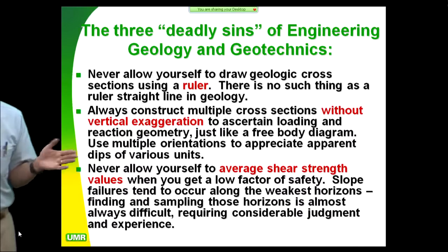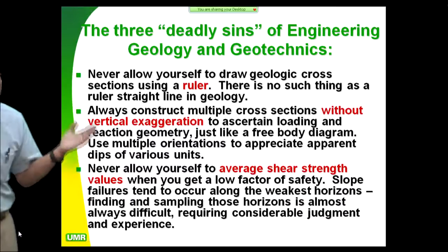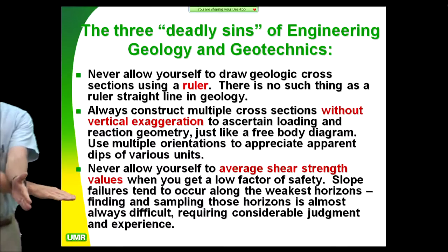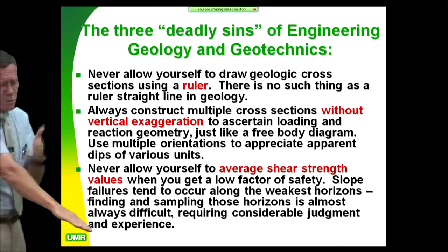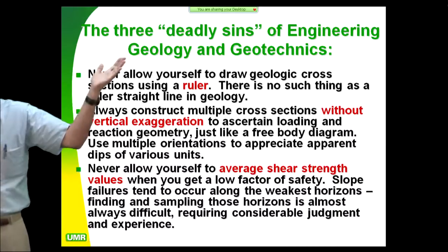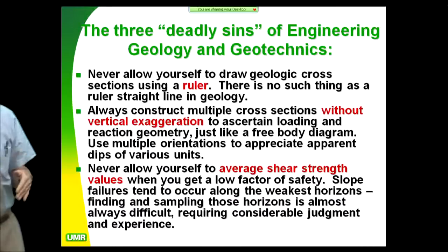Whenever I look at landslides, block glide slides, I've never had one go straight down the dip. It's always at some angle to the true dip. So the true dip's this way, but they made the cut over here, so the thing fails that direction toward the cut. Come on. It's a no-brainer. But don't do the analysis just down the true dip.